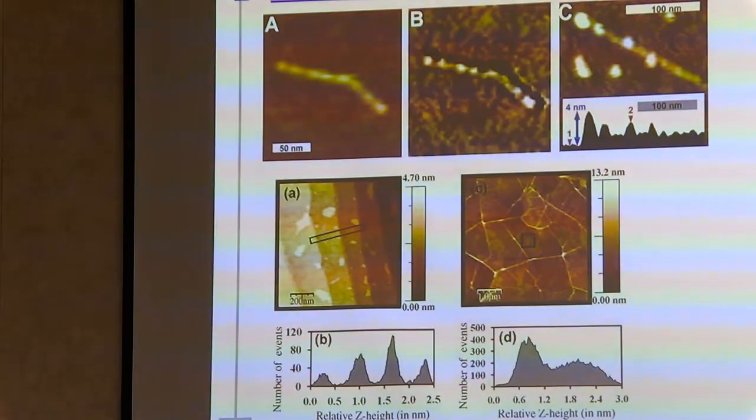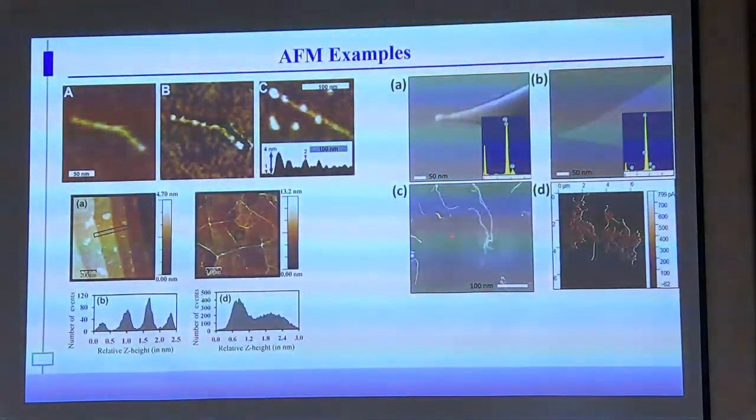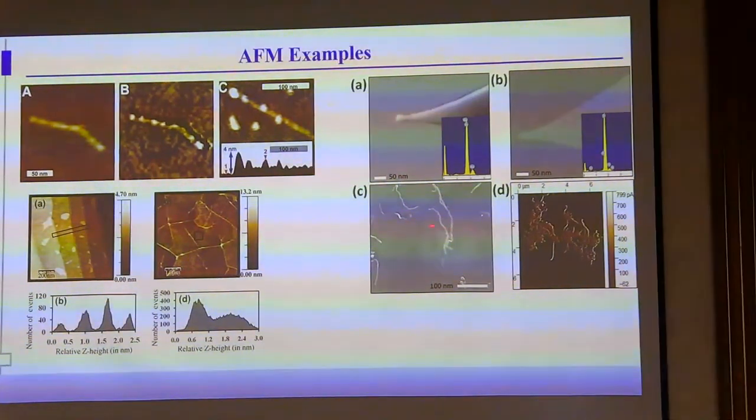The third example here is about conductive mode. Here you can see simply these tubular structures. But when you run the conductive mode, when you analyze this sample with conductive AFM, you can see a current image here. All these are the current profile, and here you can see current is in picometer. So these are conductive, and this is a non-conductive area. Not only are these tubular shapes conductive, around them they also have some conductive surface here.